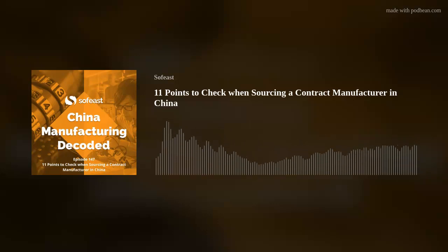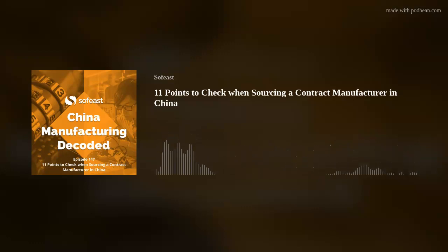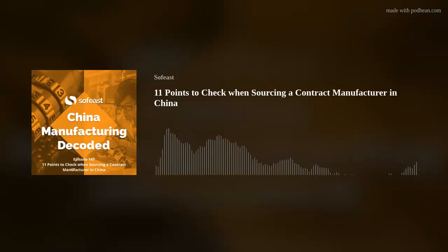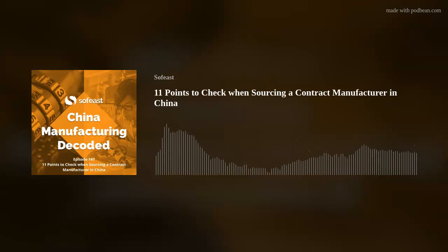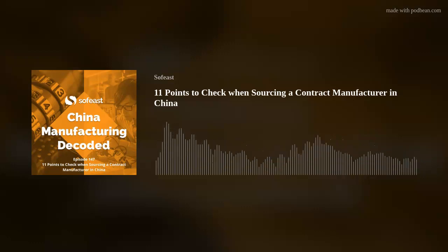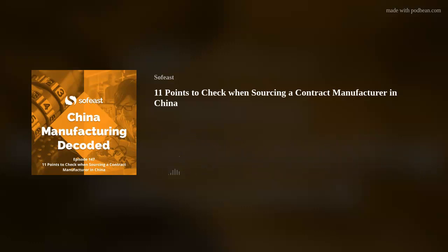And then also in the electronics industry, you might sometimes see EMS, electronic manufacturing services. You might think, what is that? Usually it is a company that does the PCBA process, assembles the components on the PCB, and sometimes they also do assembly operations. But be careful, if they introduce themselves as an EMS supplier, it means their main focus is on PCBA.